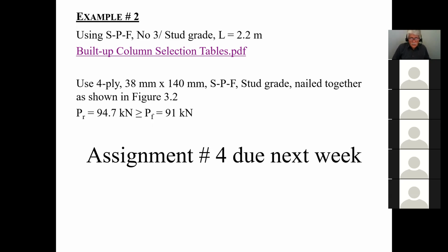You mean, in real life? No. All I'm saying is that 99% of the time, your built-up columns are going to be in a standard, dry, non-treated situation. But don't take that attitude that it's always going to be that. It can be in a moist environment. It all depends where you're designing.